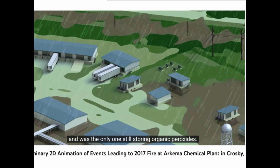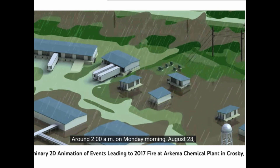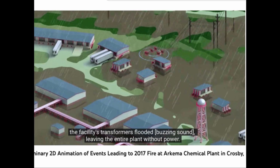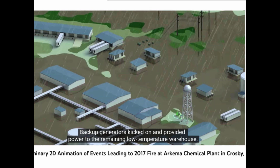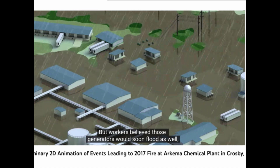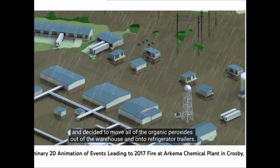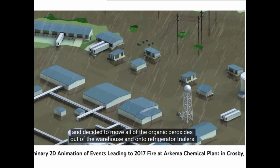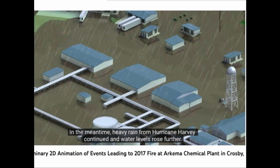By Sunday night, only the largest low-temperature warehouse had power and was the only one still storing organic peroxides. Around 2 a.m. on Monday morning, August 28th, the facility's transformers flooded, leaving the entire plant without power. Backup generators kicked on and provided power to the remaining low-temperature warehouse. But workers believed those generators would soon flood as well, and decided to move all of the organic peroxides out of the warehouse and onto refrigerated trailers. In the meantime, heavy rain from Hurricane Harvey continued, and water levels rose further.